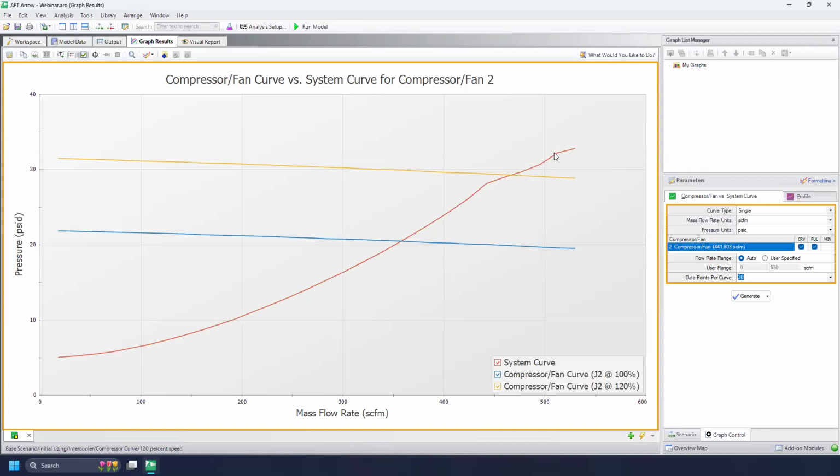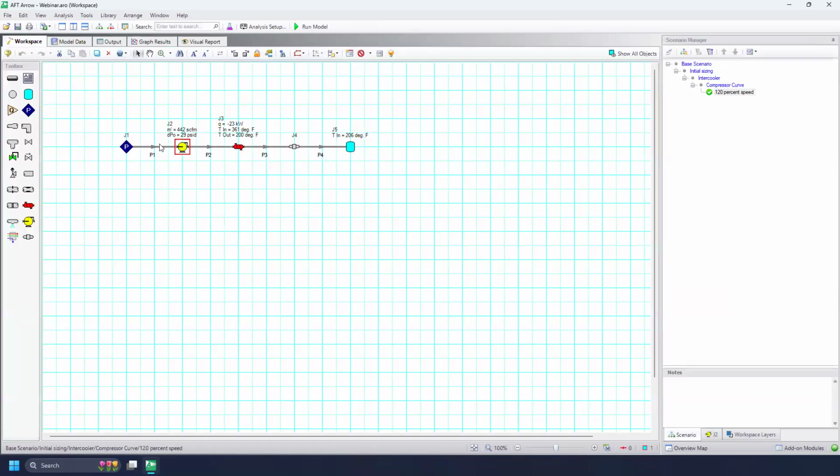And it looks like something else will choke over here as well, if we were to take the speed of the compressor further. So really, we would want the system to have a larger inlet pipe here. The rest of the pipes, when we were looking at the Mach numbers, looked like they were fine. But that's something where maybe we would make several child scenarios and figure out the minimum size that we need to keep that nice and well below Mach 1 for more efficient systems.